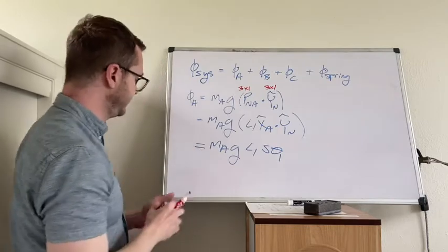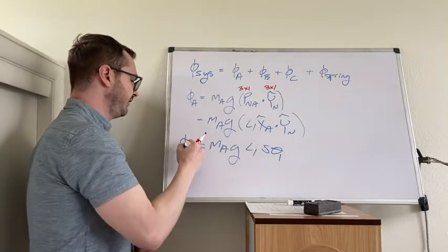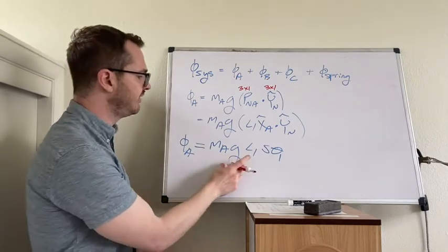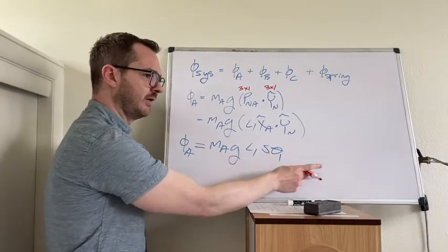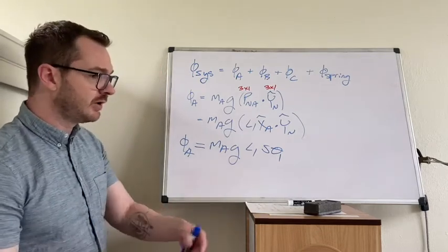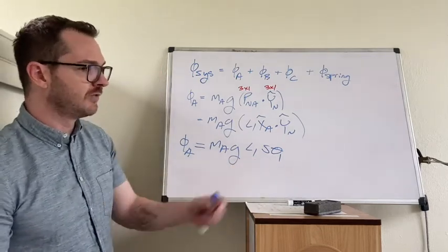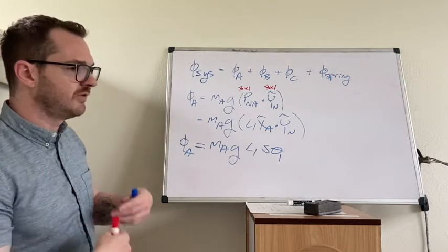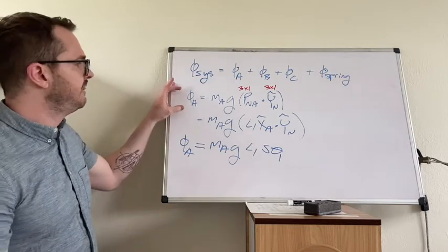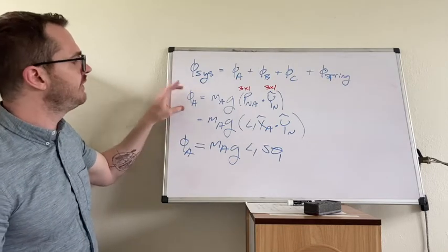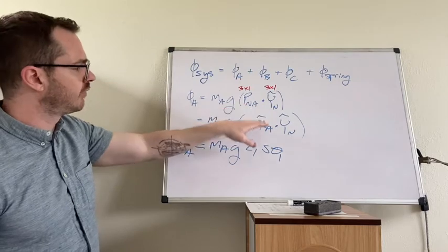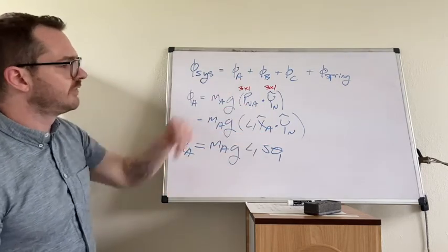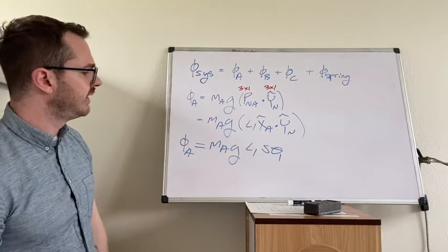And remember that energy, here is phi A, remember that energy is scalar. So MA times G times L1 times sine theta 1. Now, maybe you could just look at the problem and sort out that this was it. That's fine. You don't have to do all of these intermediate steps, but when the system becomes very complex, these steps are still always true. So if you have position vectors to centers of mass, you sort out the frames, you do the dot product, and here's your energy. So there's the potential associated with A.